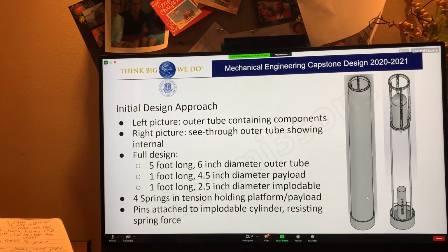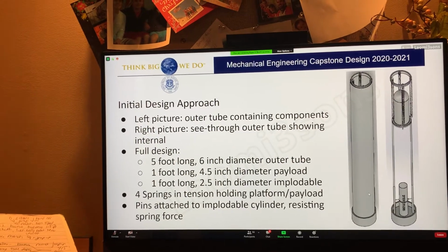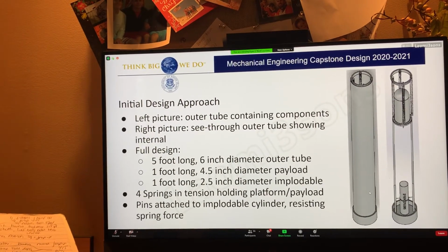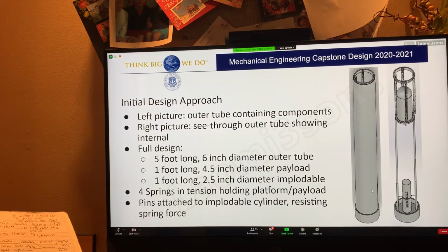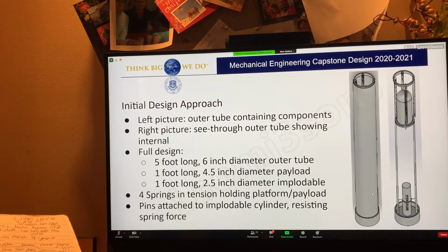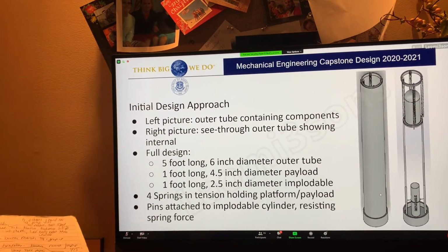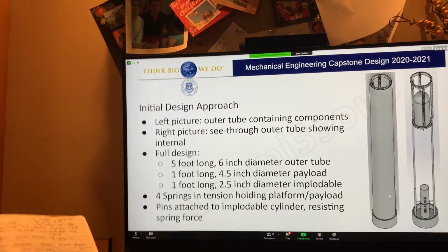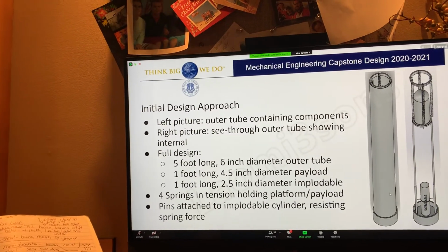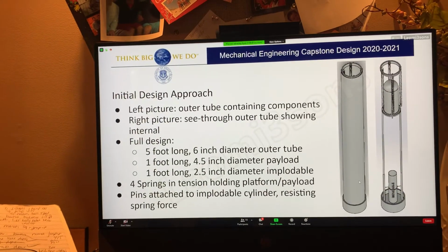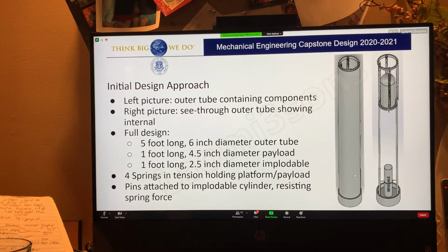These springs are also attached to a 3D printed insert part that sits at the top of the outer tube. And on the other side of the springs and the platform are 2 connecting rods made of aluminum that are threaded onto the screw hooks in the platform. Since we have such a big length in our outer tube, these connecting rods extend about 40 inches, where they are guided by PVC pipes with matching insert holes for 2 pins to oppose the spring force when loaded.